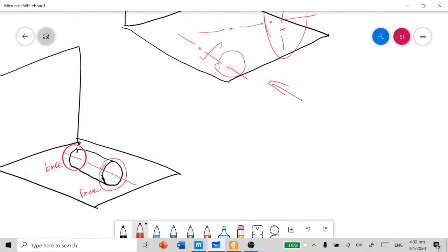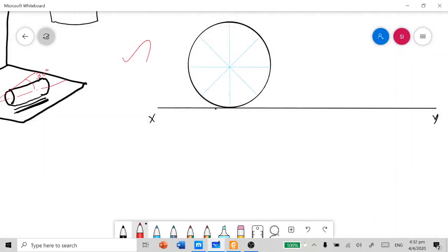If you consider it like that, the numerals come very near to you and the alphabets are far away from you. So in this way we give the names, starting from A, B, C, D, E, F, G, H, and similarly 1, 2, 3, 4, 5, 6, 7, 8, everything mentioned with a dash since it is a front view, and the alphabets go inside the bracket.